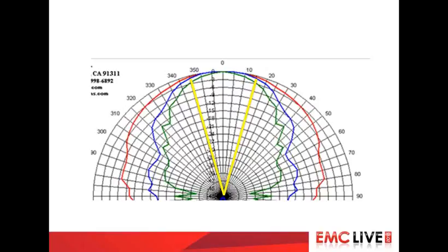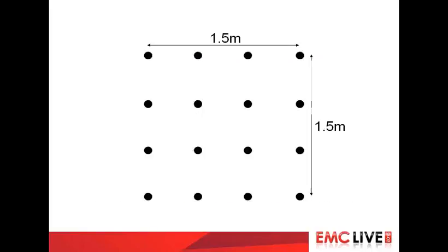We can do likewise with the one at 9 gigahertz. Let's count those off, going clockwise again: 5, 10, 15, 20, what is it, 23, 24, let's call it 24. And it's the same on the other side. So at 9 gigahertz, the half power point beam width is 48 degrees or thereabouts. And then the final one, for 1 gigahertz, has a very nice beam width of 10, 20, 30, 40, 80 degrees. Why am I saying it's a nice beam width? Well, this system has a job to do. The antenna has to illuminate this calibration plane.